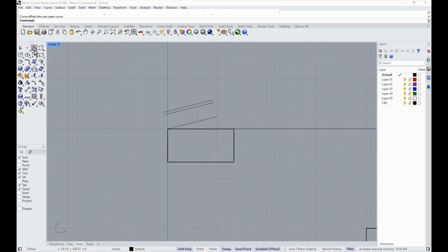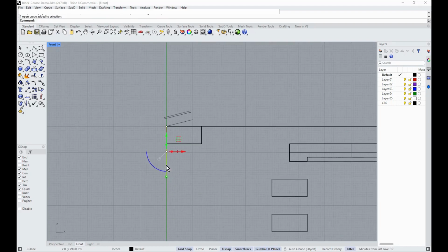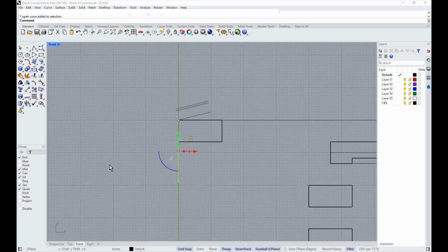Now the next thing we're going to want is, and we want to try to highlight that first line we did, we'll come down and we're going to do a 2-foot offset, which is pretty normal. Depending on what kind of soffit materials you use, this will affect this in architecture. So Hardie Plank has panels that are 2 feet wide, and you can use that under your soffit as one option. Or with stucco, it's also available in wire mesh with tar paper behind it, and they'll just staple that up and apply stucco into the structure.